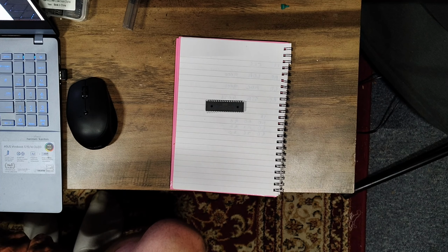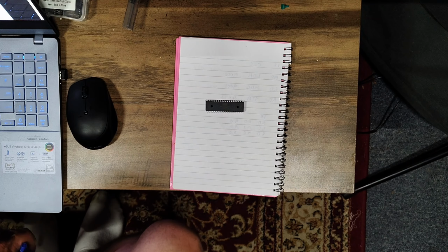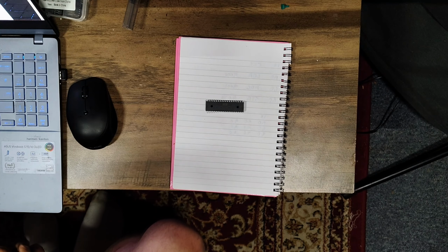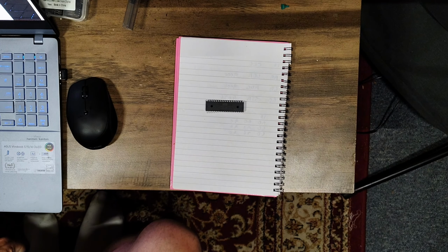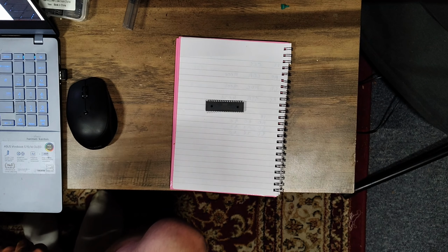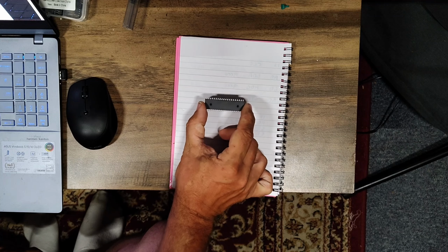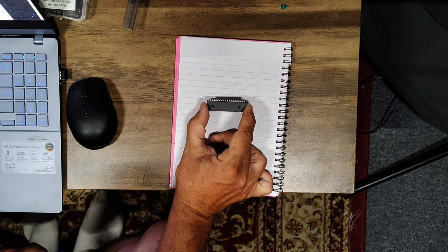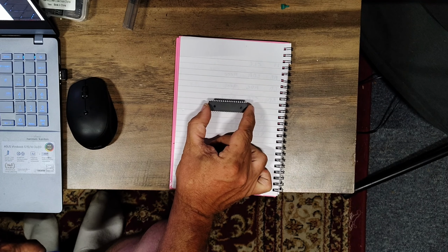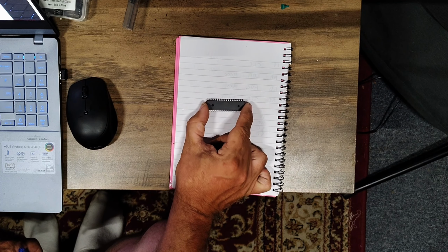Now, in the last video I promised you that we would have some form of outputting some data from our computer, not via a more impressive computer, which is the Arduino Mega, into a much more impressive computer, which is my laptop. So we're going to do it with this chip here, and this chip is a W65C22. Now, given that our processor is a W65C02, you can tell that this chip is designed to work with our processor, so it should be fine.